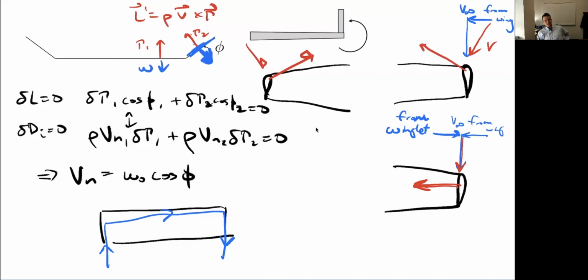Well, the reason why this is actually better is because we have only so far looked at the winglet. We haven't thought about the winglet system, right? So even though the winglet is maybe not getting as much benefit here or any real benefit, the winglet does affect the wing. So we have to look at the downwash of the wing on itself, which we already know is downwards. But how now does the winglet affect the wing?